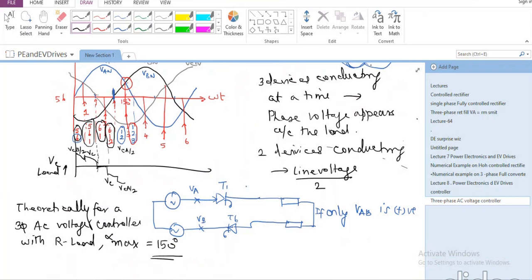And in DC to DC converters, we will be looking at the basic non-isolated converters like buck, boost, and buck-boost, and probably the Cuk converter also in the next class. But we will be looking at isolated converters in terms of flyback, half bridge, full bridge, and dual active bridge converter.